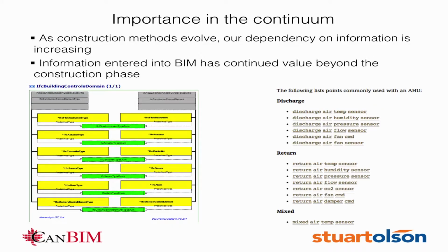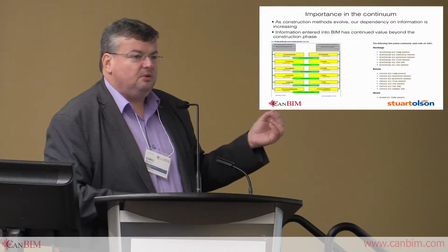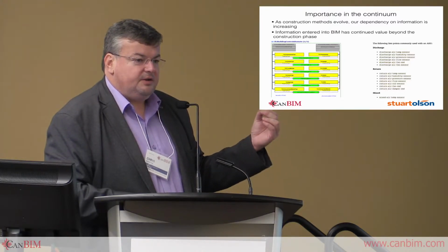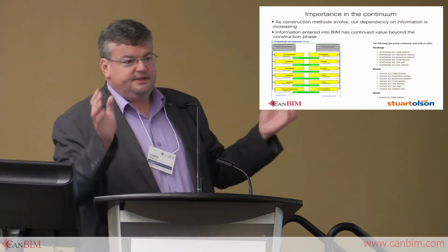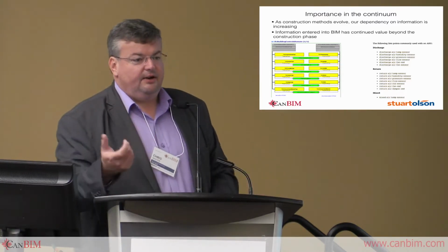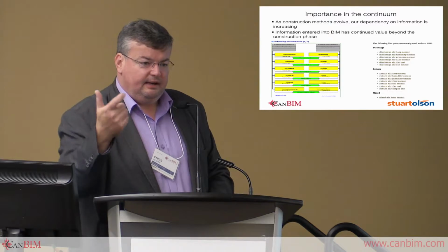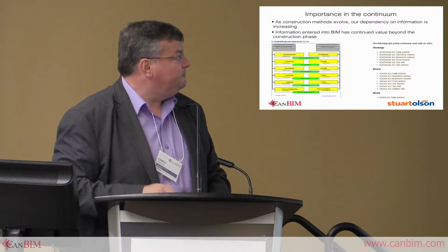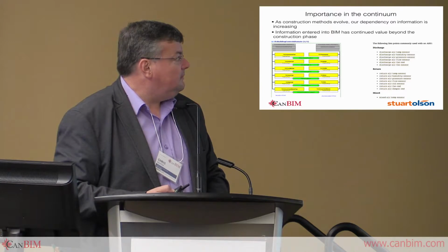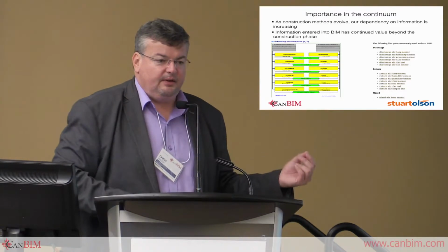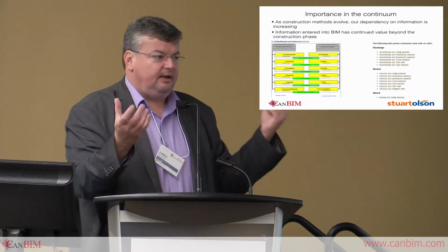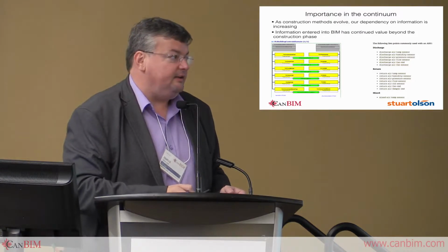So even though we have the same objects on the left-hand side, on the right-hand side, the Haystack methodology allows us to provide a more natural language, and also has context and description. So you're not guessing at what AHU-146419 might be. You know, it's an air handler. Here are the temp sensors for those objects. And that's probably one of the hook points. When you have somebody at the other end receiving BIM that needs it for their operation, it fortifies what BIM is required and needed to do.